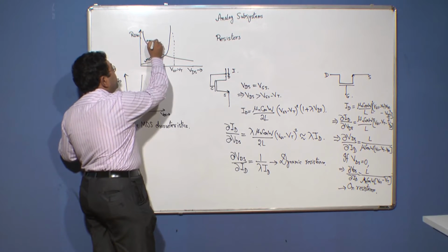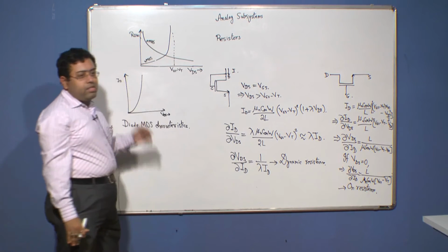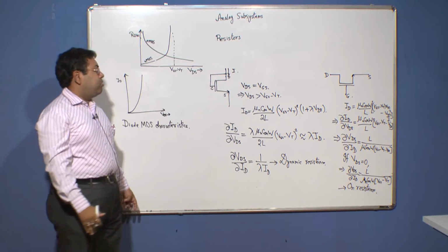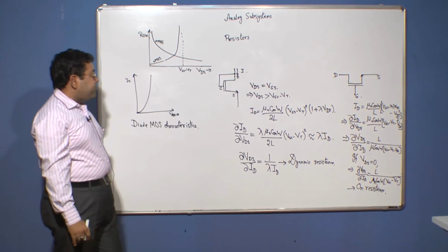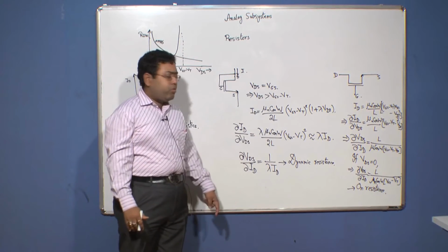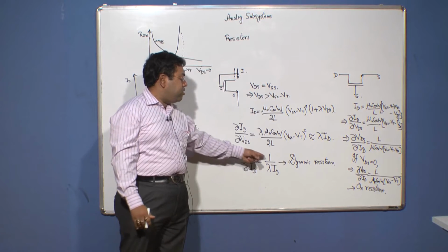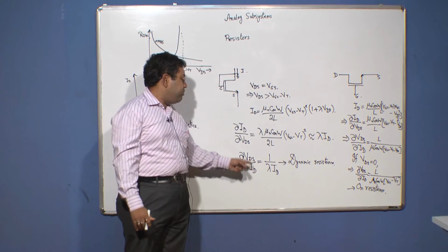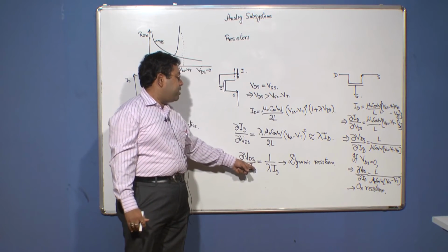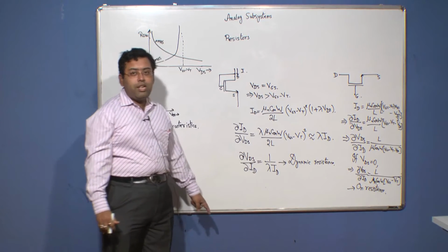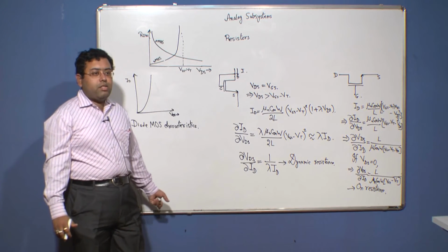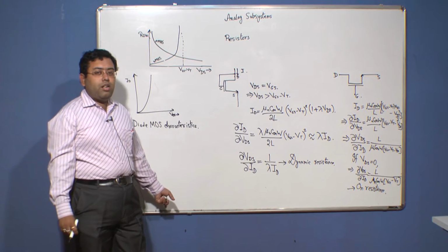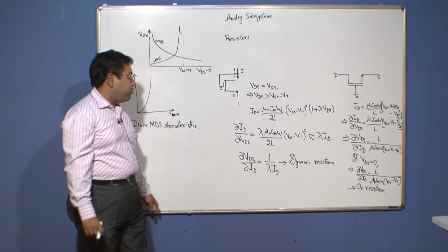So, if you consider the behavior of these resistances versus the normal ohmic resistor, these resistors are highly non-ohmic, and this is also mathematically evident from this equation, where you are getting a voltage to current relationship which is inversely proportional to the current flowing through the resistor, which is very much a departure from Ohm's law.